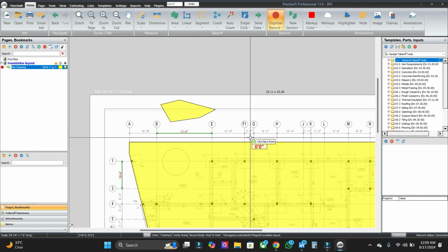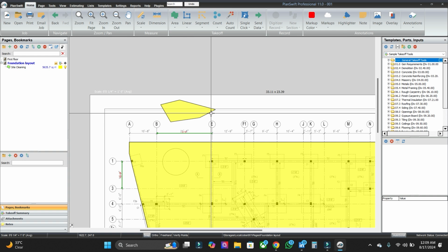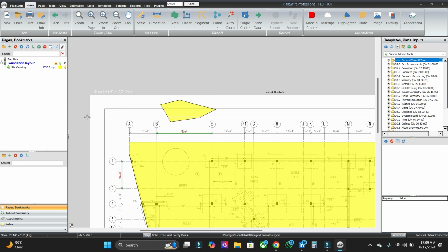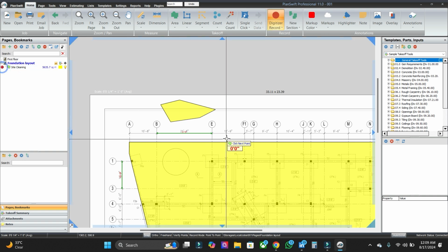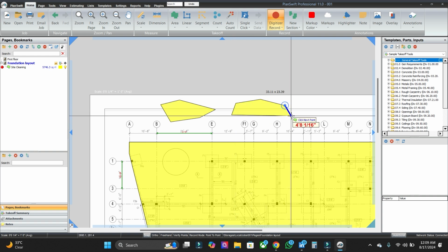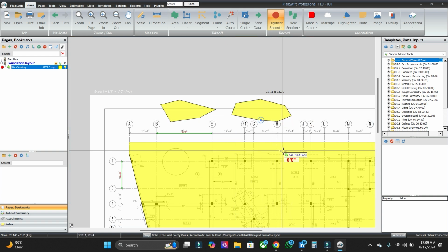After completing the measurement, press the escape key to deselect the current layer. Measure an area using the previous layer again. Find the previous layer from the left side and look for the green icon. Click on this icon to start your measurement and continue it by clicking, and double click to finish it.